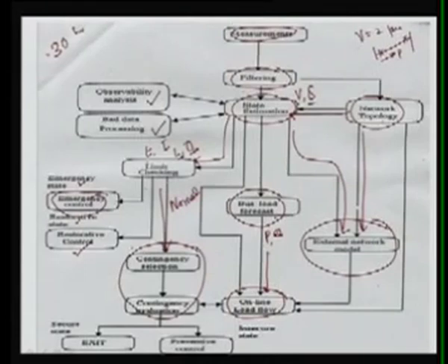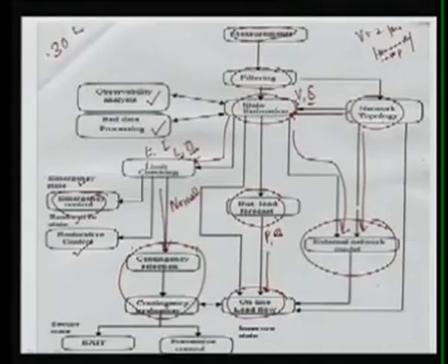As I said, your power system may be connected with other neighboring systems, and it is not possible to go for analysis of the whole system. So it is convenient to form that external network with one or two nodes, and that is called the external network model. We have to model it in such a way that it will not hamper your power system studies.